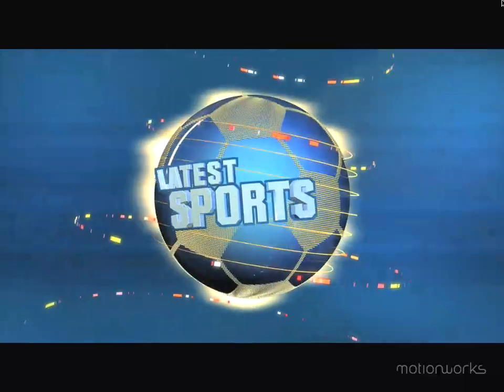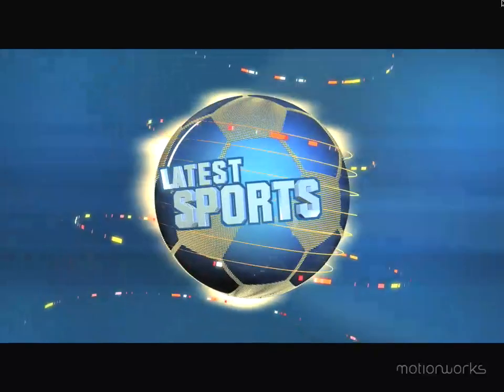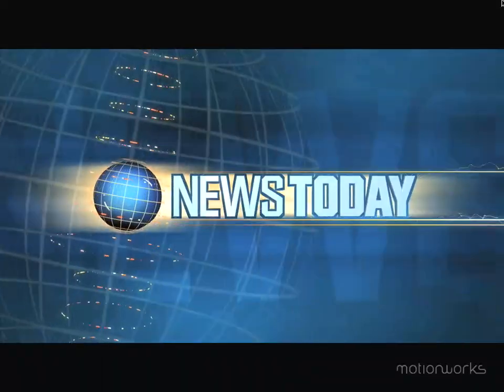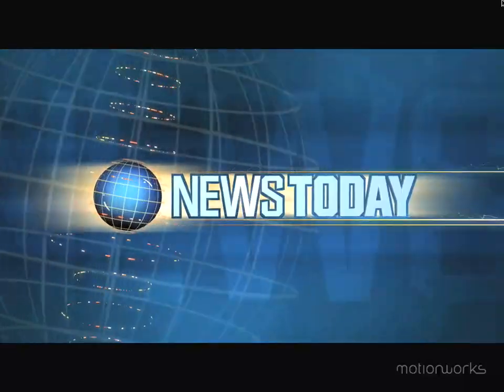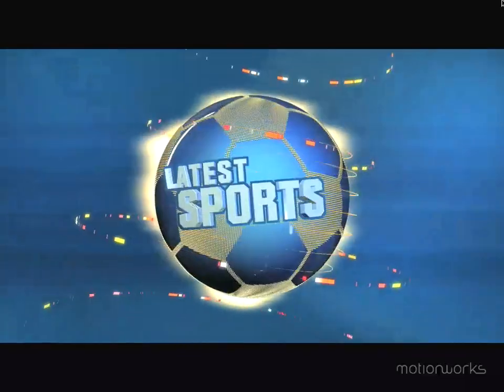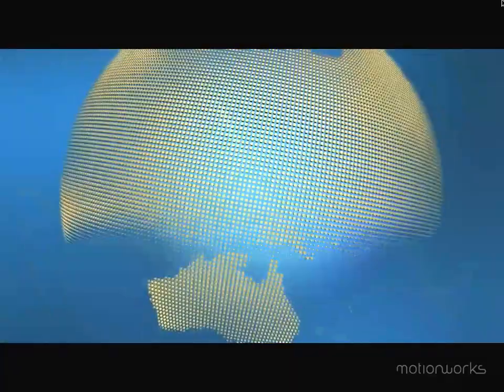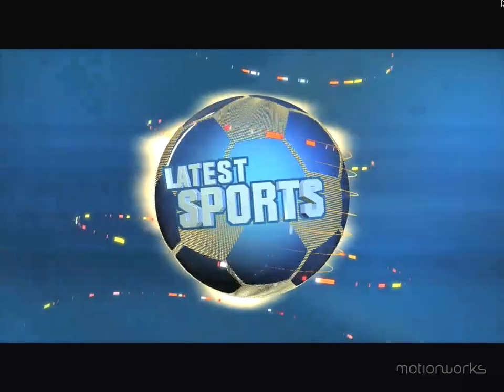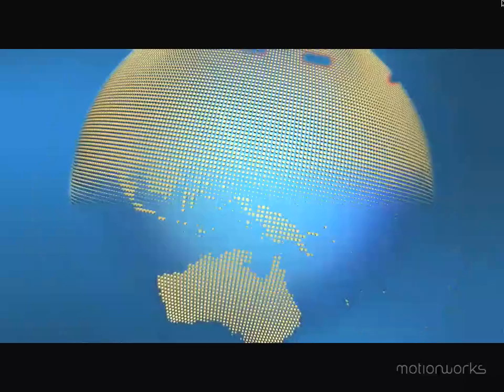I also hope that you've learnt a lot through this tutorial. We worked in Cinema 4D and we went through quite a few options in the MoGraph module, specifically working with the cloner, and we used the cloner in object mode, and we also looked at cloning radial mode and using cloners within cloners. We used various attributes of MoGraph, including tracer to make our sweep NURBS and our glowy lines. We used various effectors as well. Along the way we created quite a few different materials, and we had a look at lighting using include and exclude.